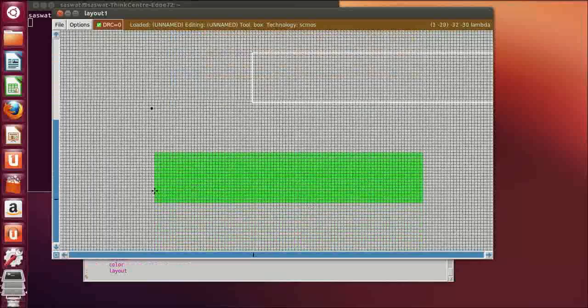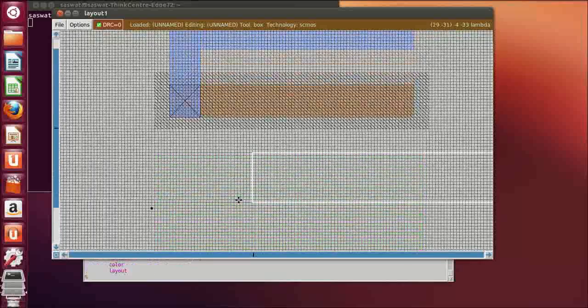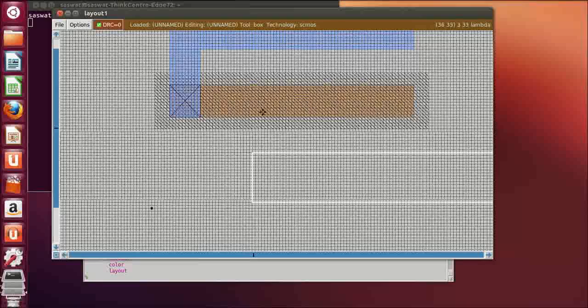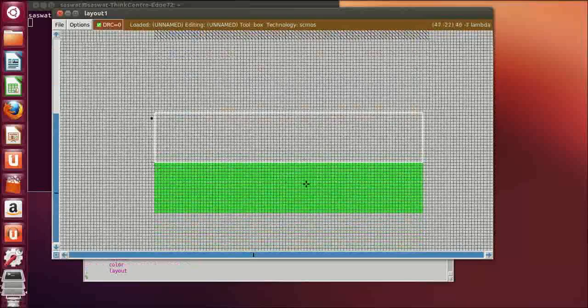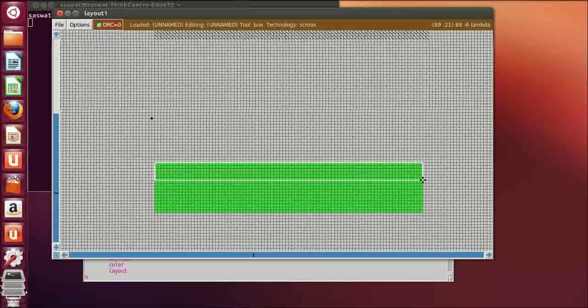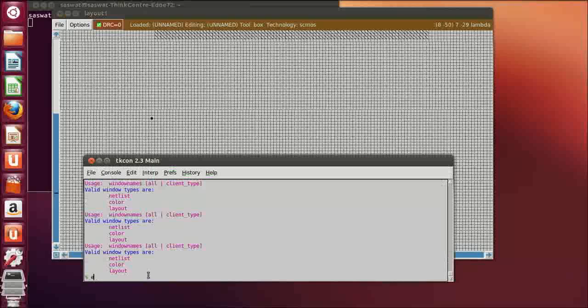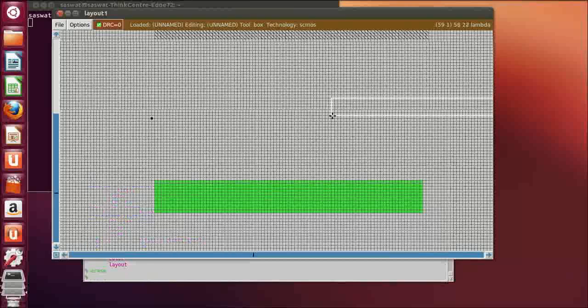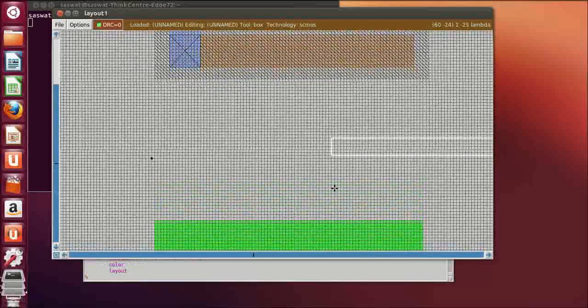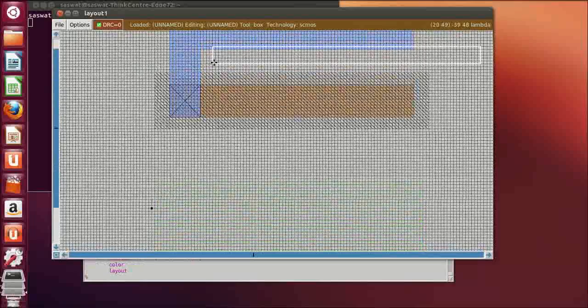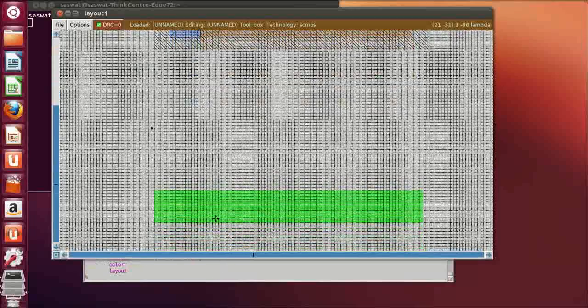I think this became too much. You can see the width of the P diffusion layer. So similarly, this should be less, in the same width. So this got erased with the help of the erase command. Now we have to make a poly contact.